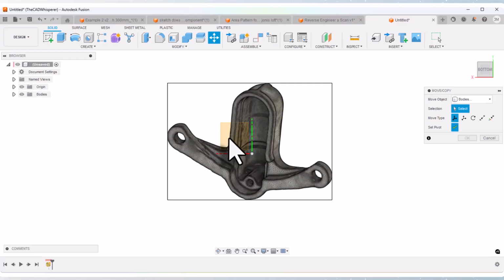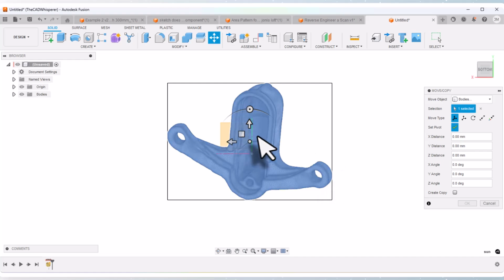And so I'm just going to select this plane, and I'll find a point here. And now notice that this is parallel to that plane. I need to say done here. So this is the most common error, to forget to select this done after selecting the pivot point. And so I'll select that done.